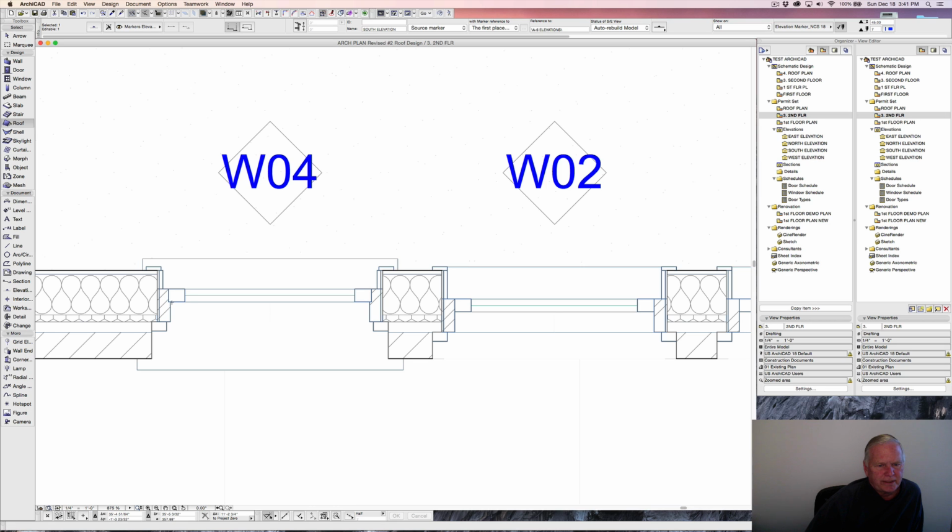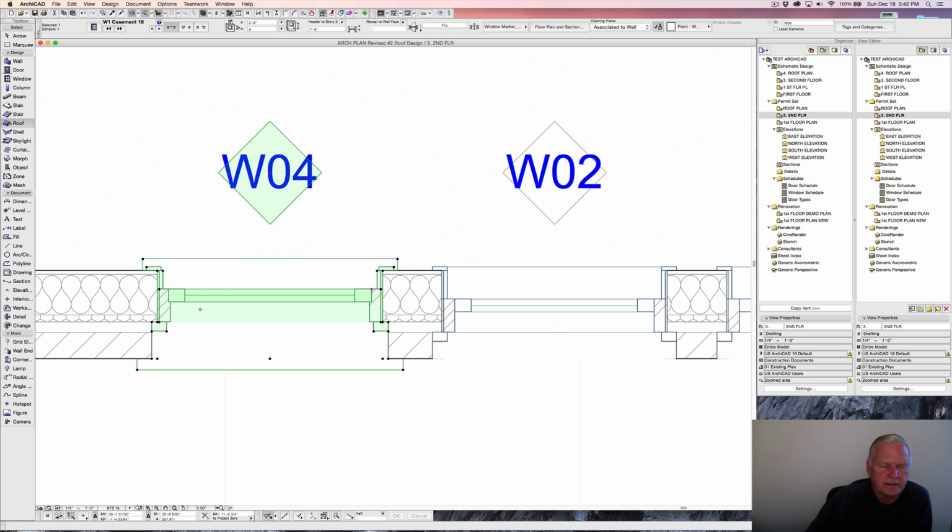Anyhow, as you can see, this is now shown reasonably correctly, except for the fact that this window and the rabbet that's in here would then indicate that this casement unit would enter to the inside. And actually, I'm going to show you something. On these windows, you can decide that, hey, I want to show somebody that this really operates, and you want to. So graphically, you can open it and put it in an open position, whatever you want, 90 degree all the way. However, this is not the way, at least in the US, for most all casement windows, they would open out.